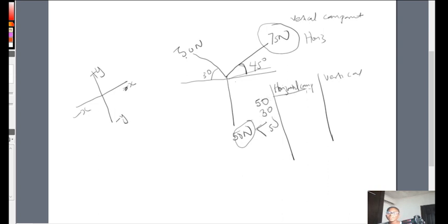So these 3 forces, 50 first for the horizontal component. Is it along the positive x-axis or along the negative x-axis? As you can see, 45 is here. This is the positive x. So it means this is going to be positive. So what are we going to use? For the horizontal, we use the cos. The vertical, we use what? We use sine. So here we just be what? The angle, which is 75. That will be 75 cos 45 degree. That is not going to be a negative sign.